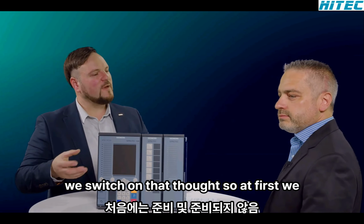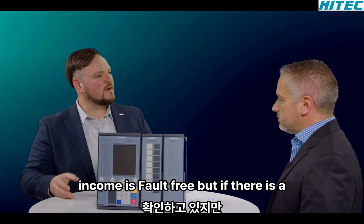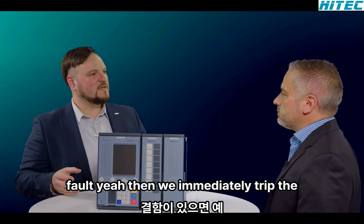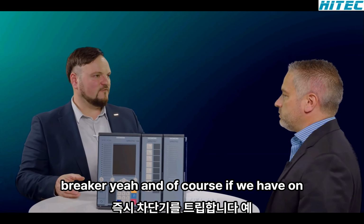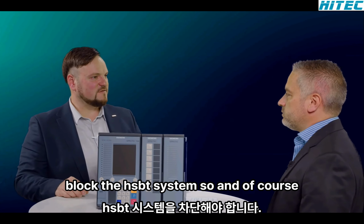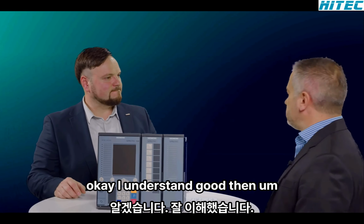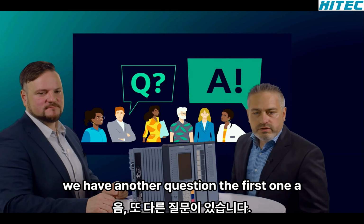At first we have a readiness and unreadiness check, so we are checking that the alternative incomer is fault free. But if there is a fault, then we immediately trip that breaker. And of course, if we have a fault on both incomers, then we have to block the HSBT system. And of course, in that case, we lose the motor bus. Okay, understand. Good.